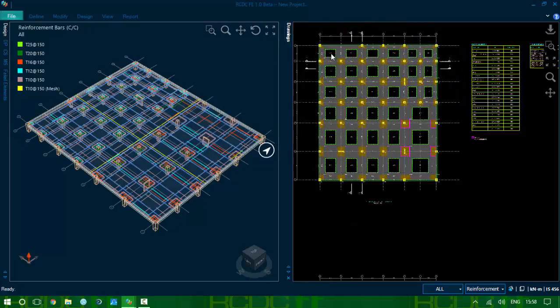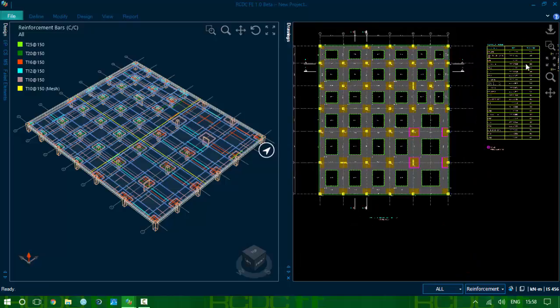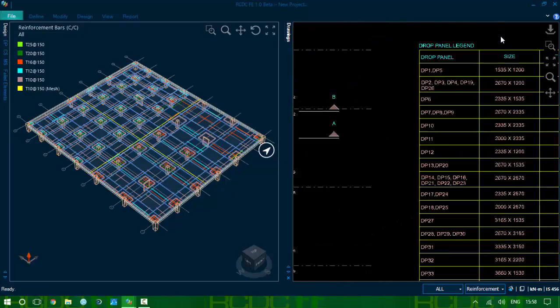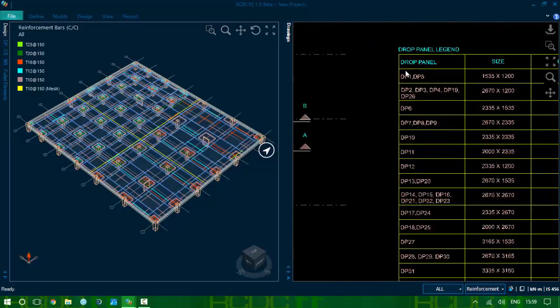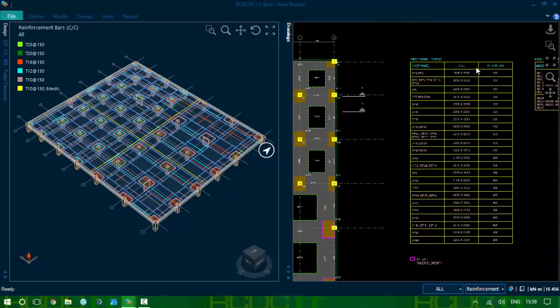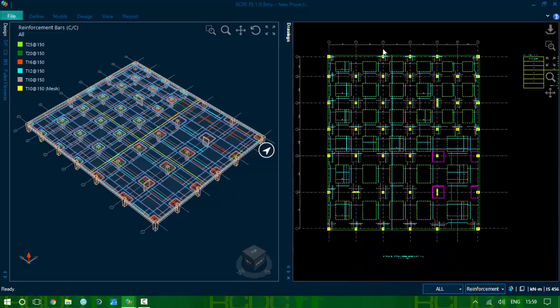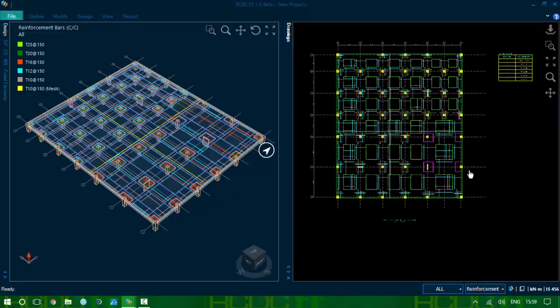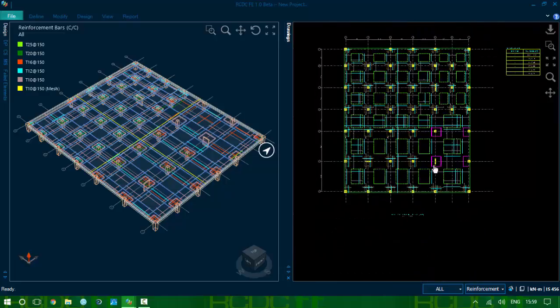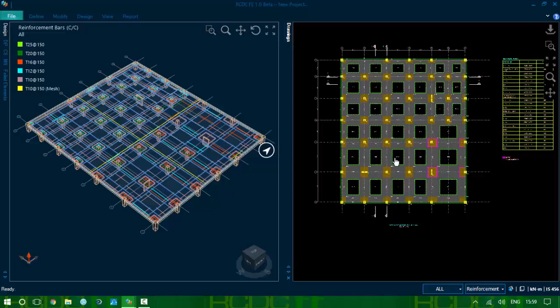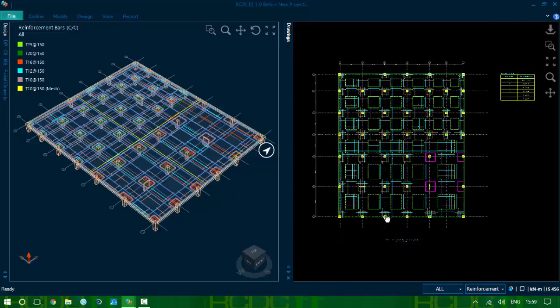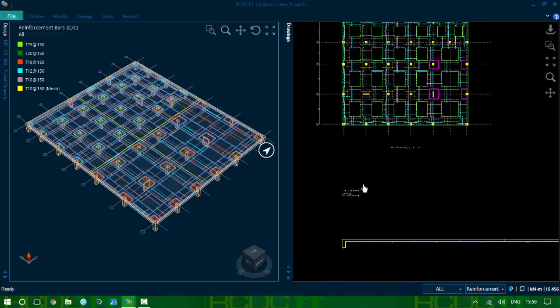You can actually see a layout. So the plan layout is here. I can zoom in here, and there are a lot of tables that define the size and the thickness of various elements and so on. If I zoom extents and do zoom in here, you can see a bottom reinforcement laid out here, and if I pan up, you can see the top reinforcement. Of course, if I go to the first view, you can see the section marks are indicated here, what we defined, and I can go in and say okay, the sections are dropped.